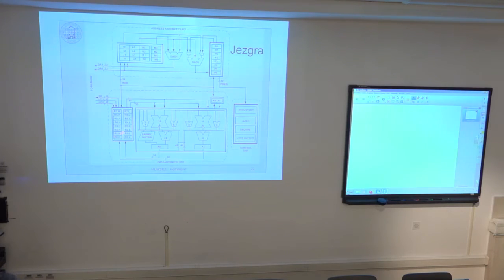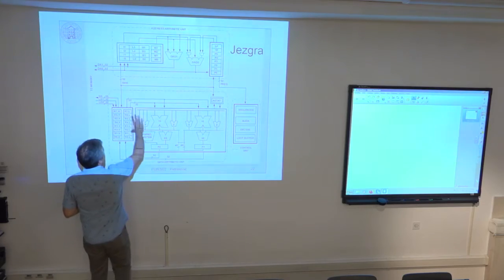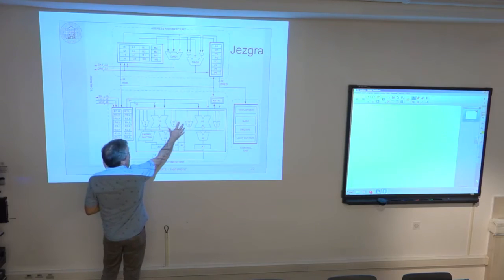If I say R0 is the argument of some instruction, or I can invoke as an argument only the upper word or lower word of this register, R0.H or R0.L. In the instruction, I can select two such 32-bit registers as arguments for multipliers.